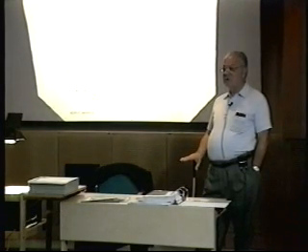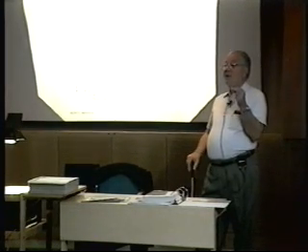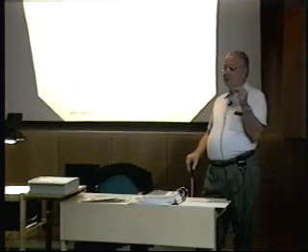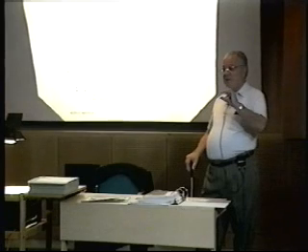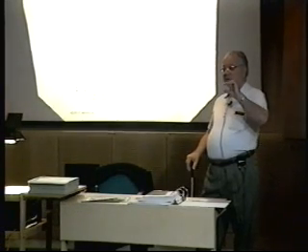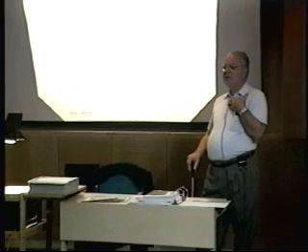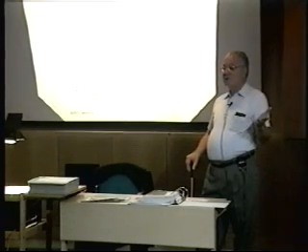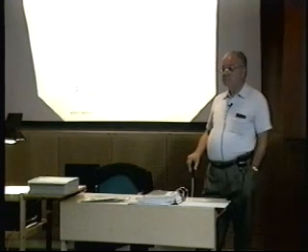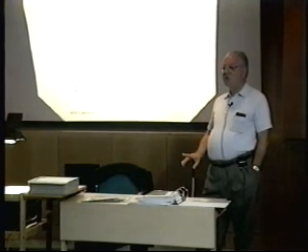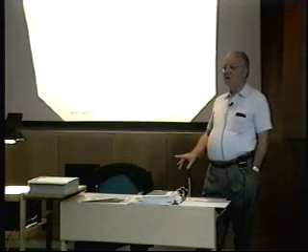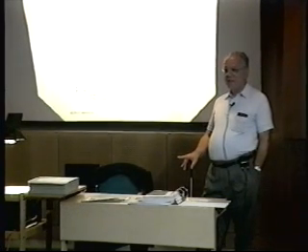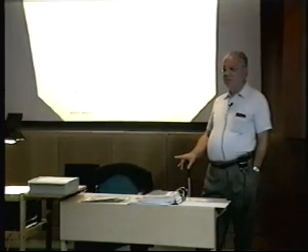Carbonate reservoirs, if you start to understand, I talk to geologists about how they're laid down in blanket reservoirs and cyclical. The majority of the carbonate, in fact, I'll make the general statement, all carbonate reservoirs are layered no cross-flow reservoirs. And you should start with the concept of layered no cross-flow reservoirs is the rule, it is not the exception. Start with that, and you're going to eliminate a lot of potential disasters in reservoir engineering.